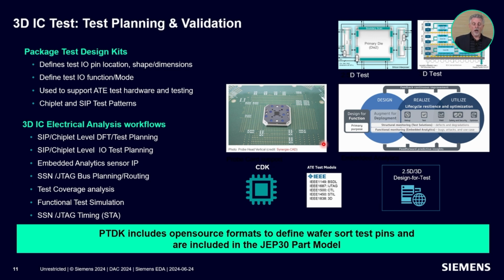So here, the package assembly design kits would define the I/O locations. This, again, is carefully coordinated between the test teams, the DFT teams, the chiplet designer, and the package designer. And then once those test pins are defined and located, they're put into this machine-readable format, and that can be used to go off and build the test hardware and such.